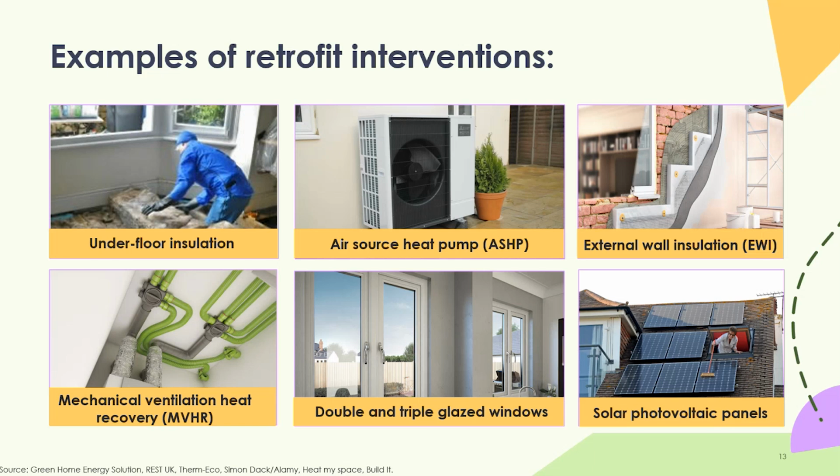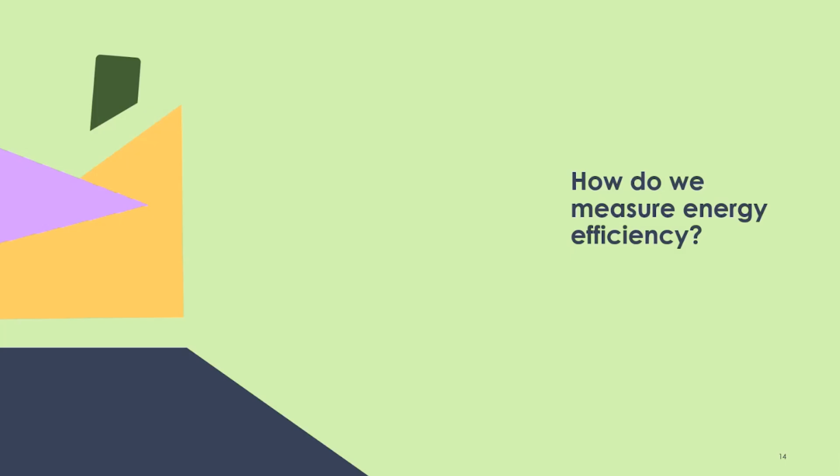Ventilation, that's a bit of mechanical ventilation with heat recovery system. Tend to get MVHR more on new builds or very high level retrofits where you're dealing with a lot of air tightness, but it's not the only ventilation system out there. And a really important part of retrofit is the ventilation strategy, because it impacts so greatly the damp and mold, the humidity, and therefore the health outcomes for the property, as well as preventing damage to the fabric of the building from excess moisture. So yeah, always important to remember your ventilation strategy, and it's a key part of PAS 2035.